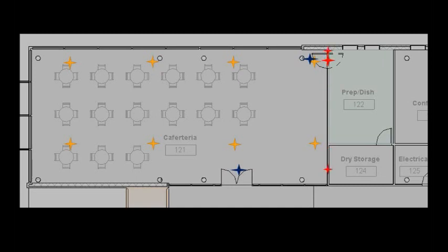So now for the thermostats. Again, we'll do the same thing, find one of the doors in the room. Now we're going to find the two endpoints for the wall that it's hosted on. Find the one that's longer and move it that way. Now we're avoiding putting it in that corner, usually the long way where it's open. So we'll go down that way a little bit. And then again, we'll get the normals to the wall. And now I'll ask, okay, which one's closer to the center of the room? And that's how we'll decide which side of the wall to put it on.